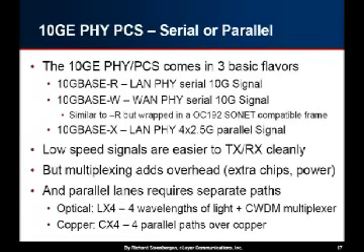And there's a few advantages to doing this. If you're transmitting a lower speed signal, it's easier as far as the electronics are concerned to transmit and receive the signal cleanly. It requires less work, less technology. But you also have to take into account the multiplexing, and that's going to add a SERDES. That's going to add potentially, in the case of optical, a small optical mux.